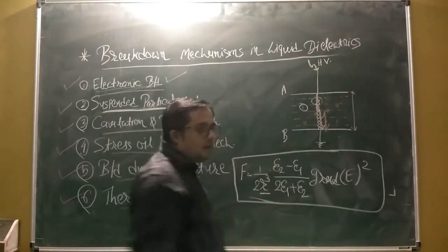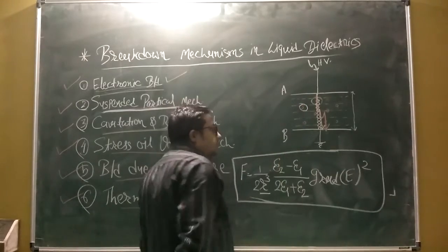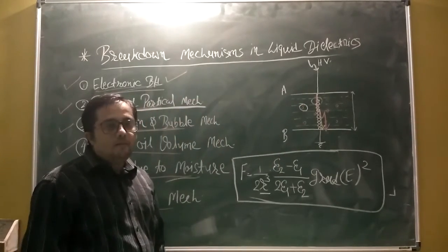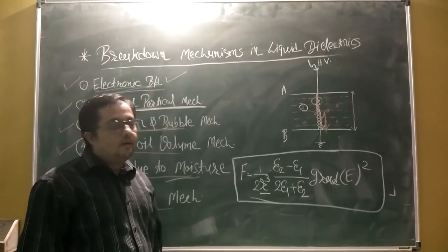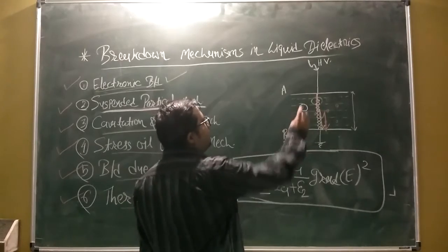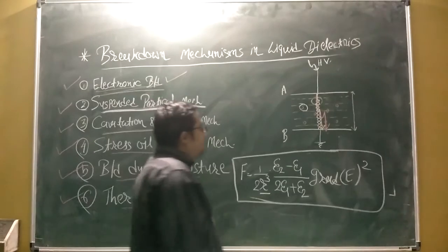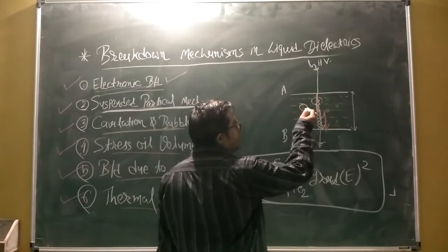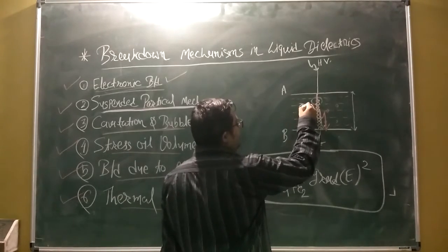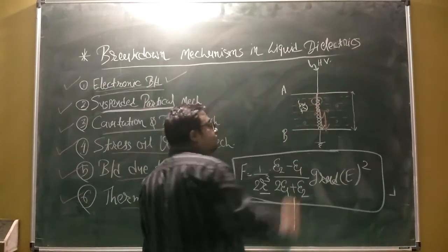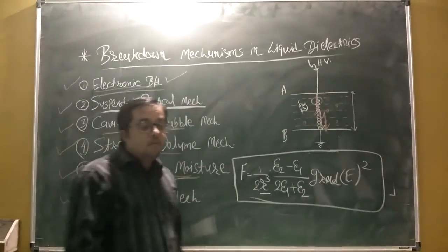When I am giving the voltage, the potential gradient at this particle becomes higher. Okay, so we can say that the potential available across this solid particle is more than its former threshold value. So it will cause local field enhancement, and as there is a local field enhancement, it will partially bridge the gap, and that is known as a partial discharge phenomenon. Okay, so once this situation is happening, what happens?